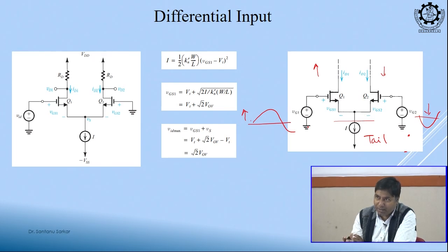I have to give the VGS, right; otherwise, if it is a BJT, I have to give the VB, otherwise it will not work. So what minimum voltage should I give? This VGS plus the voltage for this current source. If it is a current source, some circuit will be there, so some drop I have to allocate for that. You cannot think that only VGS; VGS is above some circuit.